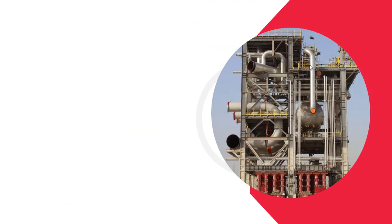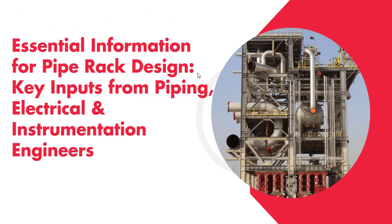So in today's session we are going to discuss the essential information required for the pipe rack design, or you can say the key inputs from all other disciplines like piping, electrical and instrumentation. See, before commencing the design of a pipe rack, it is very important to consult the lead piping, electrical and instrument engineers to gather all the following important information before you start your design. Whether it's with the available information or with an assumption of the loading, you need to take care of everything before you start designing your pipe rack in the STAAD modeling part.